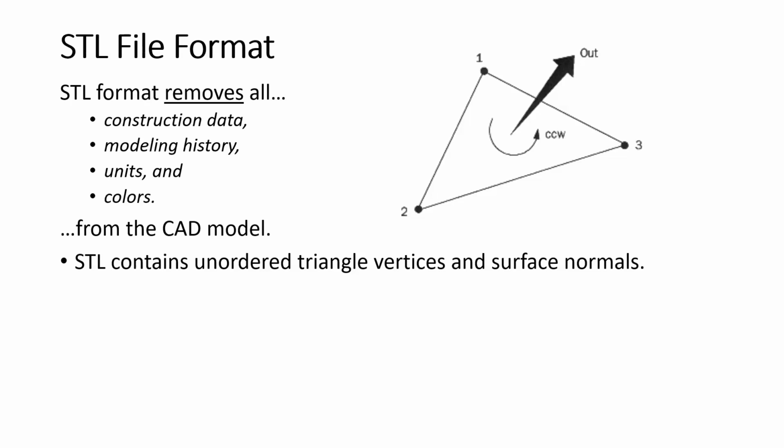Okay. And the way the computer calculates that normal is it uses basically the right hand rule. This is also done with current flow in an electrical system. You take your right hand and wrap your fingers going from point 1, 2 to 3. In this case, we're wrapping our fingers counterclockwise. When we point our thumb, that's the direction of the outward facing normal. So a counterclockwise rotation, and our thumb points out. This triangle right here has an outward facing normal, as shown with the big arrow here. So that's what each triangle needs: 3 points and a normal.